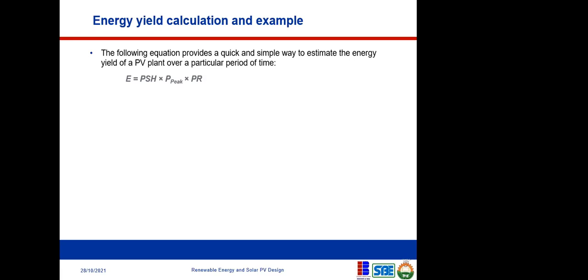Do we have data that can tell us the peak sun hour for different areas? Yeah, you can get data, but whatever data you get is maybe assumption based, maybe close assumptions. They might not be exact. So for Nigeria, depending on the region of the country, if you're in the northern part of Nigeria, maybe you can use 5 peak sun hours. But if you're in the southern part of Nigeria, it's safe to use 4. So there are close assumptions that you can use.